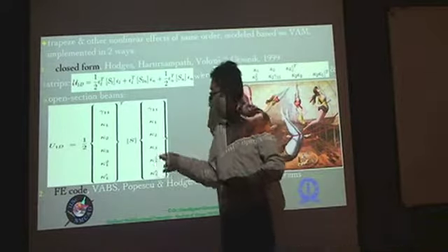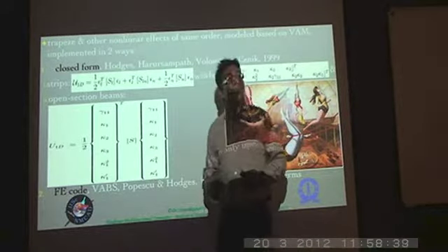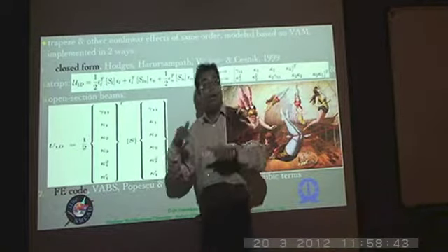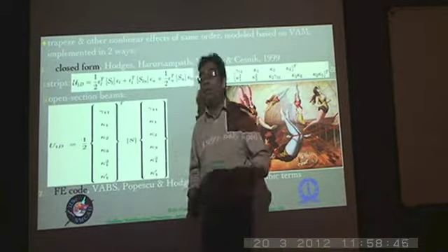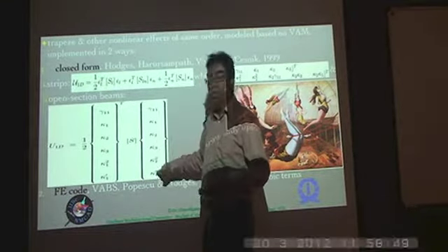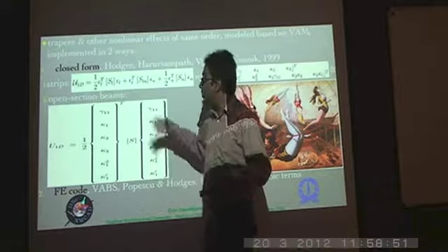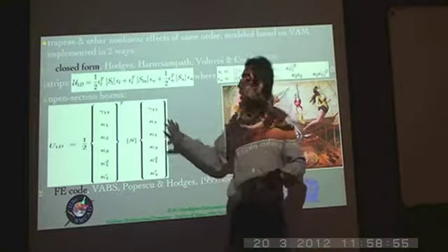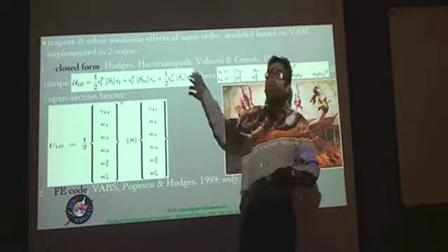And therefore you see the only nonlinear effect is basically because of kappa 1, and of course that kappa 1 squared, depending upon the actual layup you have in the composite, can link with any one of these as well as with kappa 1 prime, and therefore you get a large number of non-classical effects, but still it is not as large as what you would see here.